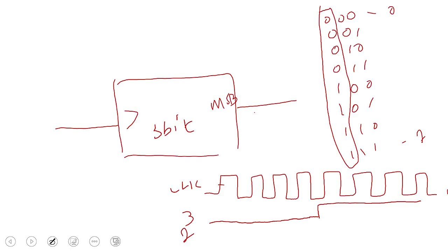So one way of dividing a frequency is to use a counter and choose particular bits to divide the frequency. Now, in that case it was straightforward, since there is 2 power 3. But suppose someone asks us to divide this 50 megahertz clock signal, to take this 50 megahertz signal and make a 1 hertz signal out of it.